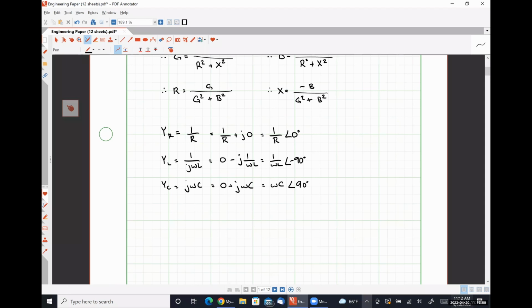Now, once we get into our electronics classes, where it's going to look like there are lots and lots of elements connected in parallel, we're going to start working with conductance quantities a lot more because the means by which to simplify them is easier. Conductances in parallel or admittances in parallel combine like resistors in series effectively. So anytime we see a sum of a bunch of conductances, we can simply treat that as, oh, it's these resistances in parallel.